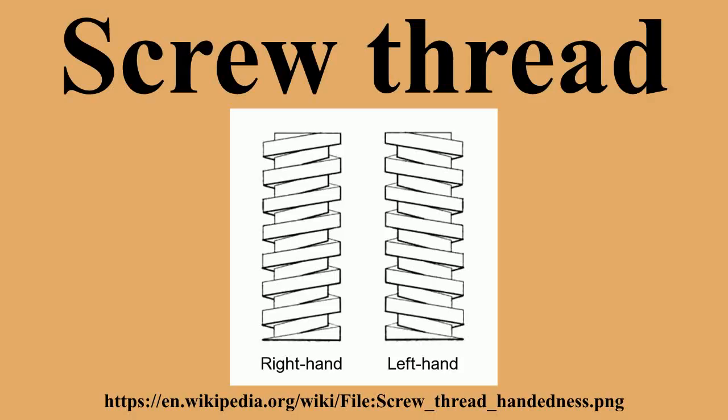In mechanisms that give a more intuitive action, as the lead screw of the cross-slide of a lathe, to cause the cross-slide to move away from the operator when the lead screw is turned clockwise. The depth of cut screw of a Stanley-type metal plane, for the blade to move in the direction of a regulating right-hand finger. Some Edison base lamps and fittings have a left-hand thread to deter theft, since they cannot be used in other light fixtures.